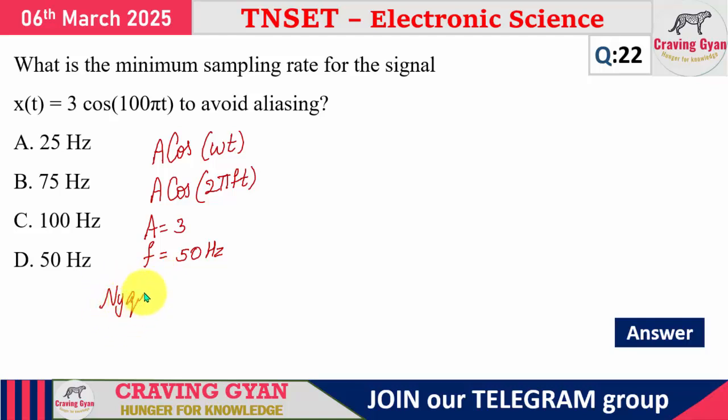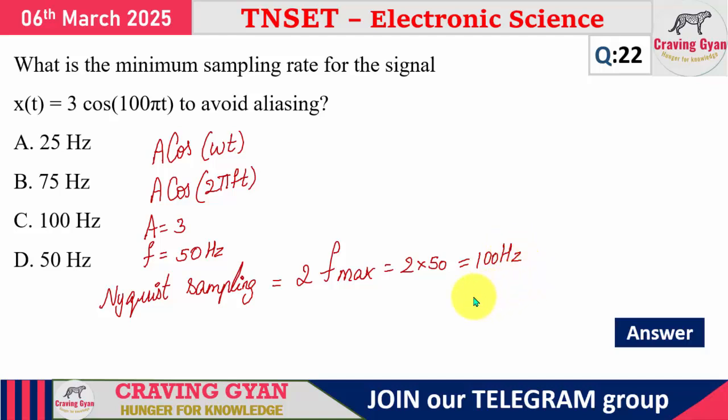In the case of Nyquist sampling, what will be the sampling rate? It will be equal to 2 times the highest frequency component of the message signal. What is the highest frequency component? You are going to get 50 Hz. 2 times 50 will be the minimum frequency, which is 100 Hz. So for this, option C is correct.